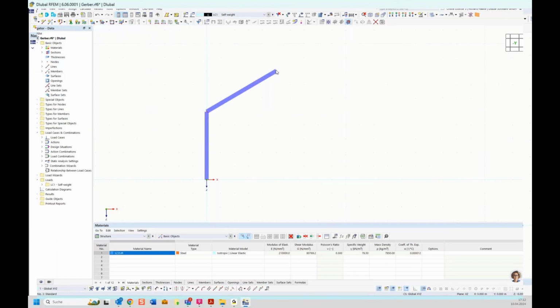So you have the option, okay, you draw 2 other beams, but I will show you another option. Here it's fast, but when you have a big hall and all is symmetric, you only need to model one half and the other you can make here. You can mirror the objects, and now I will show you how it functions.